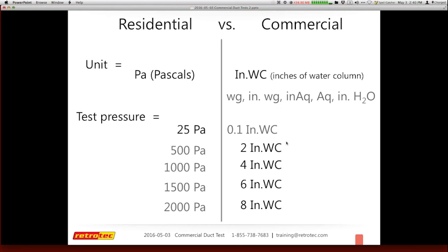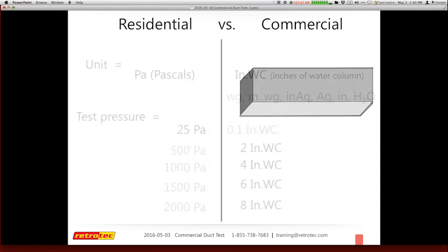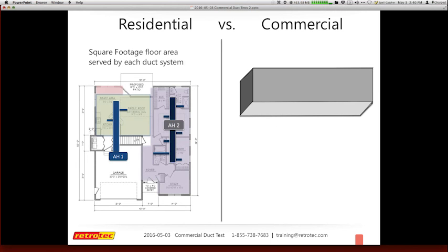So it's only when you get up to 3 or higher that we're actually dealing with what's considered high pressure, and whether or not you're going to test that. So for low pressure here, there are amendments in the ICC or Title 24 that give you guidance. If you're following SMACNA, it says your pressure is too low to bother with. Here, the code doesn't have exact compliance in terms of what it does, but it does refer to SMACNA standards,